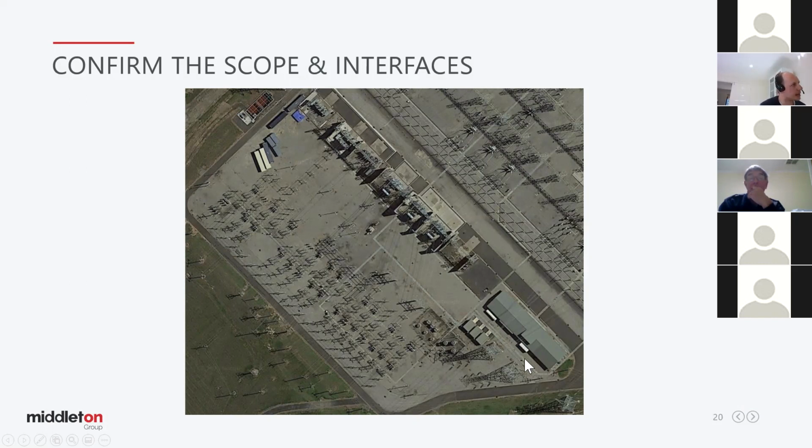Those CTC or ITC interface boxes, which we just looked at, are situated down in this bottom right-hand corner of the control room. So we need to actually confirm, are there existing trenching arrangements in place? Will our project install additional? Are the trenches full? Is the segregation in the trenches all looking okay? How will the cables get from the transformers to the control room?